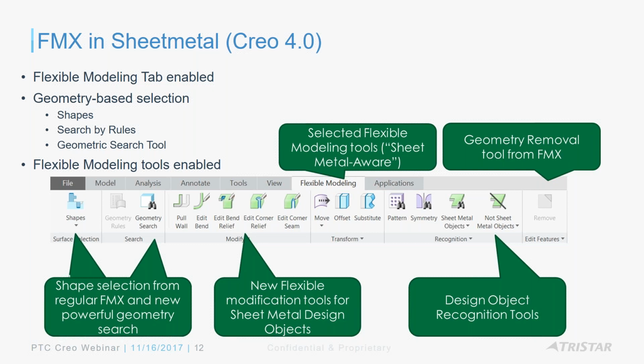So now what you could do is you could have an imported file or a file that's already done in Creo. It doesn't matter, right? You should be able to, again, do some shape selections like we talked about earlier. You could also have some very Sheetmetal specific objects. So you can say, I want you to identify all the bend reliefs, all the bends in the Sheetmetal design that is a STEP and edges.